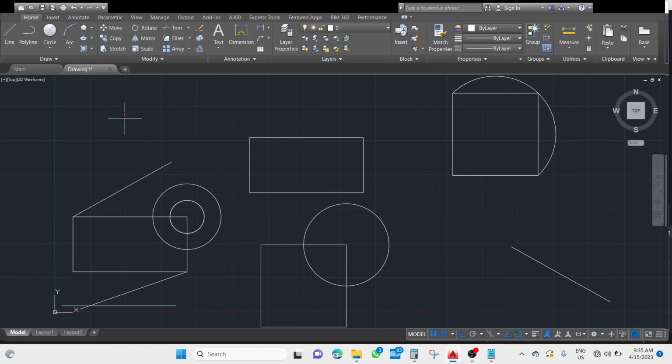Now let's see, it will ask me to specify the center of the polygon or edge. But in normal conditions we know the length of the polygon. It means I have to draw a polygon of 50 mm side, or a polygon of 80 mm side, like this. So here I know the length of the edge of a polygon. It asks me about the center, but I don't know the center. I know the length of the edge of the polygon. So that's why I am pressing E, because in the word edge I have the E in blue color. So I'm pressing E, pressing enter.